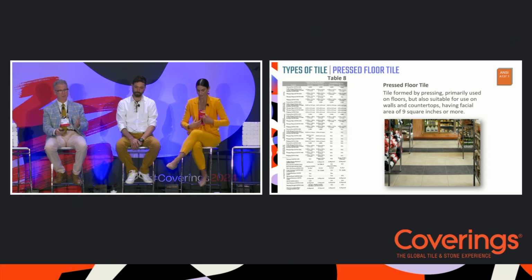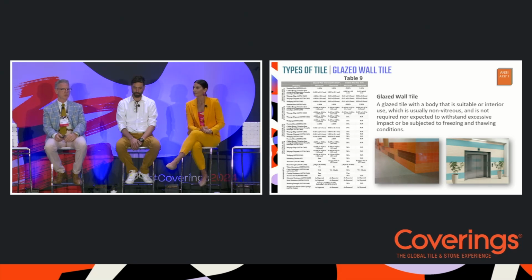And of course, you can use a floor tile on a wall, but you would never want to use a wall tile on a floor. So pressed floor tile, it's a pretty good versatile tile. Glazed wall tile, you would only put this on a wall.